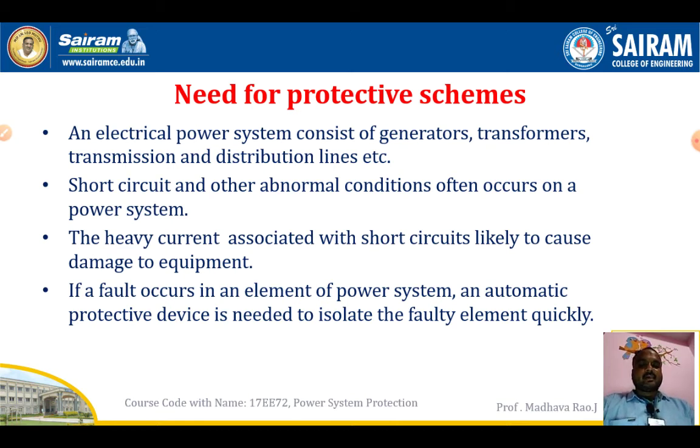These devices automatically isolate the faulty part or faulty element quickly. The operation of automatic protective devices is faster than manual operation. So automatically it will isolate the faulty element and protect the healthy section of the power system.